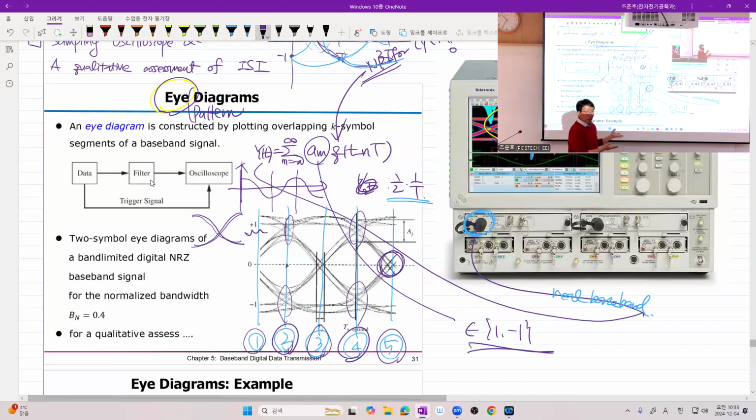So in this way, we can formulate a lot of different problems, but anyway, definitely your received signal is not a Nyquist pulse, right? Because you observe some effect of intersymbol interference, even though you sample properly, right? Mathematically speaking, a Nyquist pulse must give you a single point here and a single point here. After proper scaling, exact +1 and exact -1. Of course, after scaling. Got it?